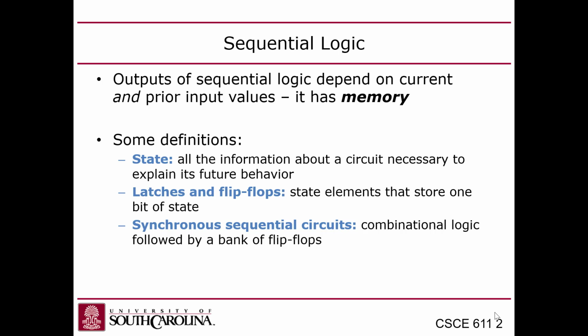And when that happens, you have to make somebody wait. So a bus controller would, for example, have a state where you request bus mastership, and then there's a state where you're waiting to receive the mastership, then there's a state where you actually do the transaction, and then there's a state where you go back to waiting for a request.